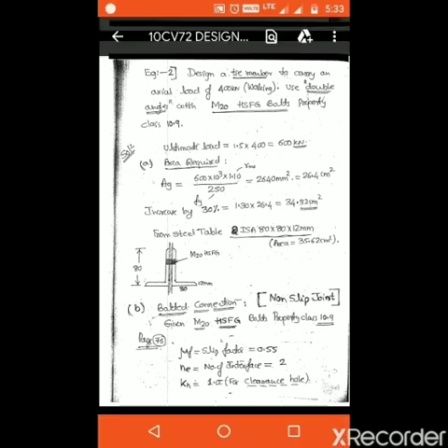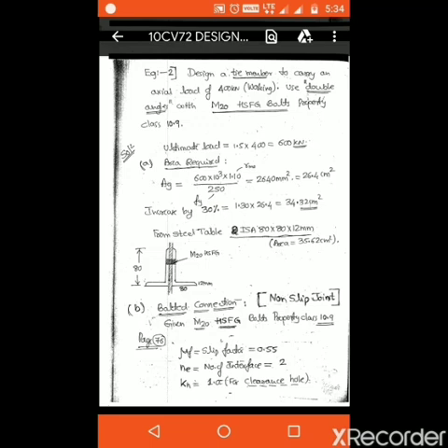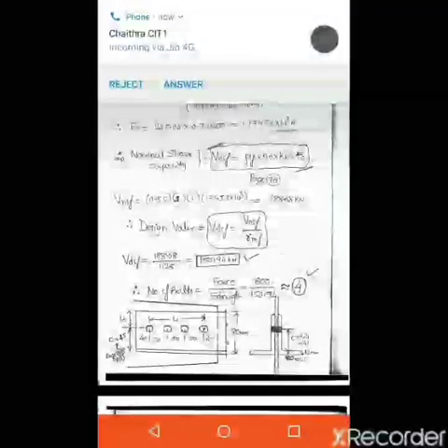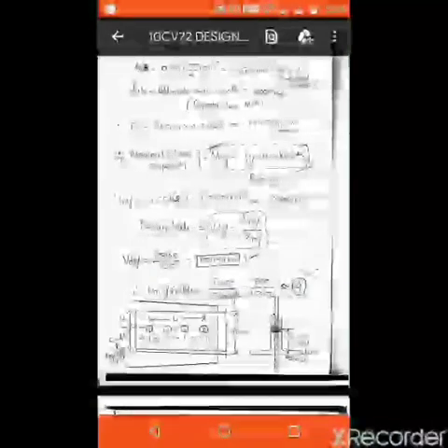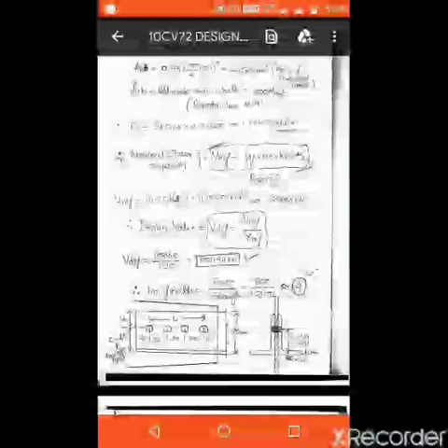Ne, if it is a single angle section, the Ne value is 1. If it is a double angle section, take number of interfaces 2. Then Kh equal to 1, it is always constant. It is also available in the equation. Now to calculate the proof load, F naught equal to proof load. To calculate F naught, always consider the shear plane within the thread.